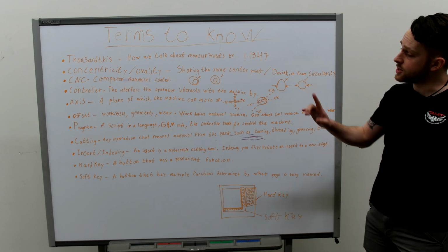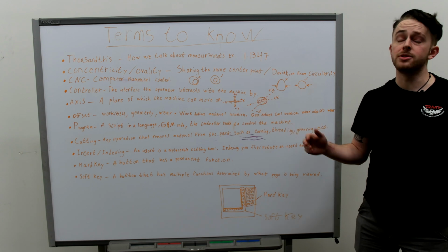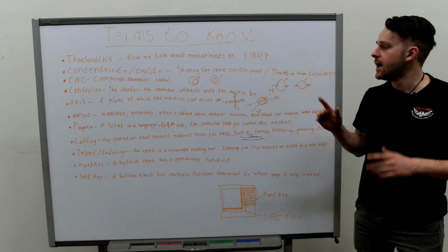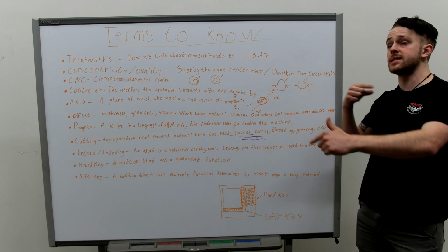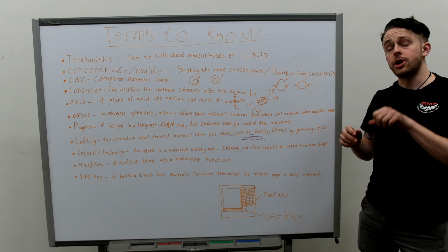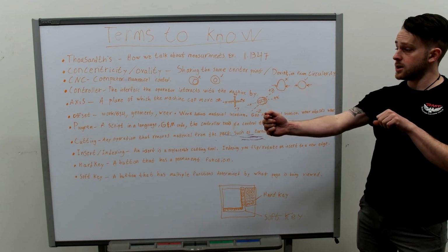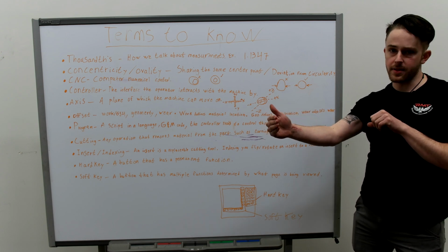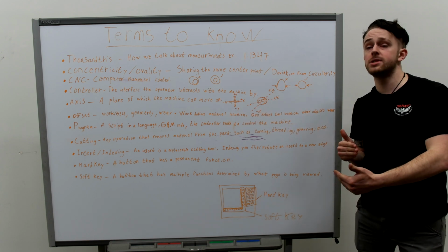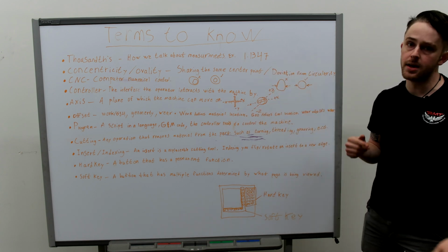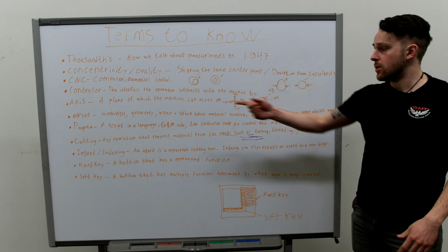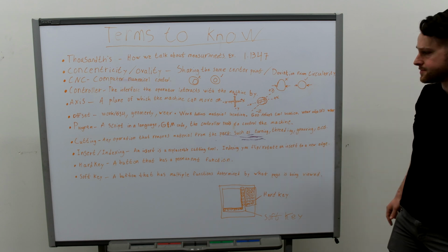But it is important to note the difference between wear and geometry, because they are both on our tool, right? They are both a tool offset. However, the geometry defines where it exists, and wear defines how worn down it is. So if you go and change your insert later, but you altered your geometry to compensate for that lack of material cutting, then when you put your new insert in, it's going to cut way too heavy, and you might not remember what numbers you altered to what numbers. So that's why we have wear offsets.